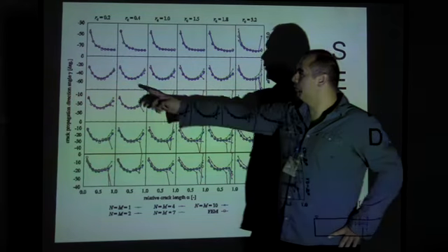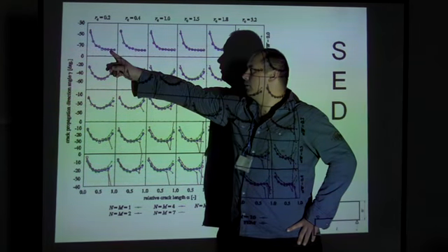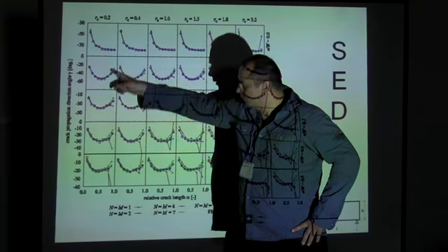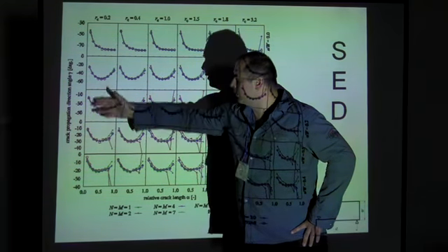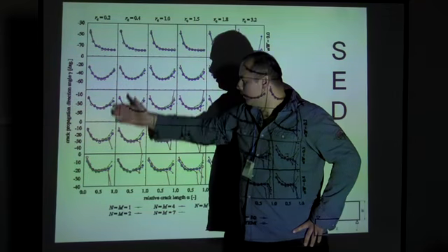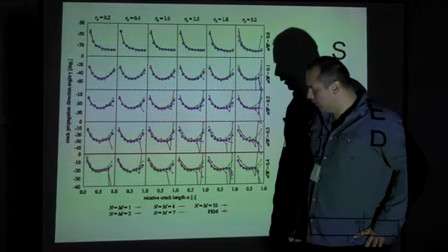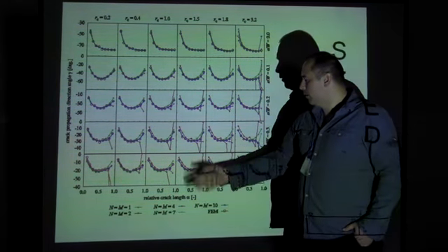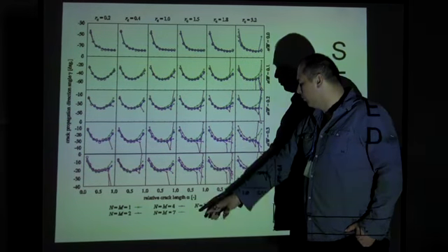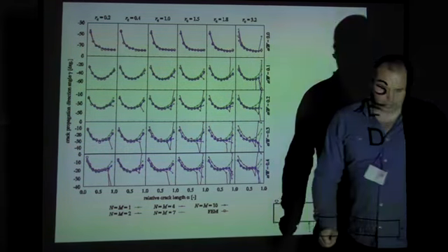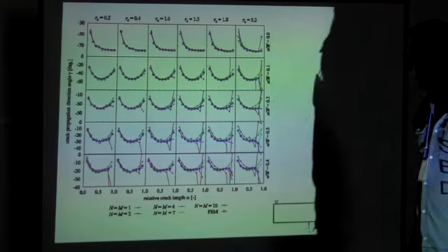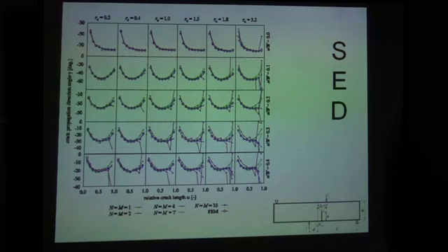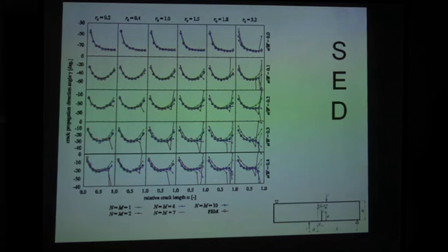But for the first seven relative crack ratios, we always obtain the same line for all values, not only for classical fracture mechanics, but for two-parameter and multi-parameter fracture mechanics, up to values from finite element methods that we obtain for an infinite number of parameters.